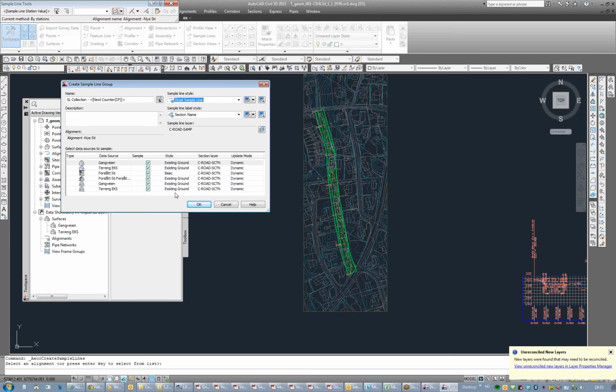If you see those little arrows in there, those are the data shortcuts. So you can uncheck those two because we've already referenced, promoted them, whatever. And the style for the surface.